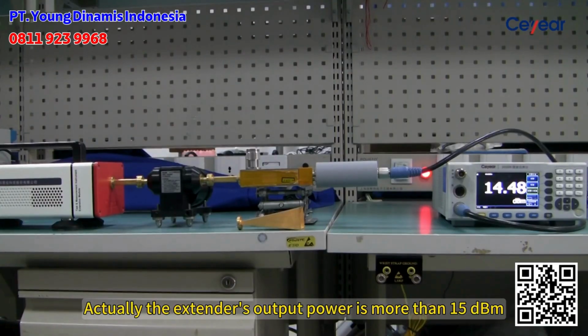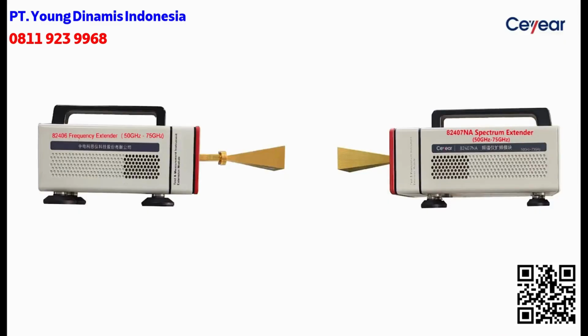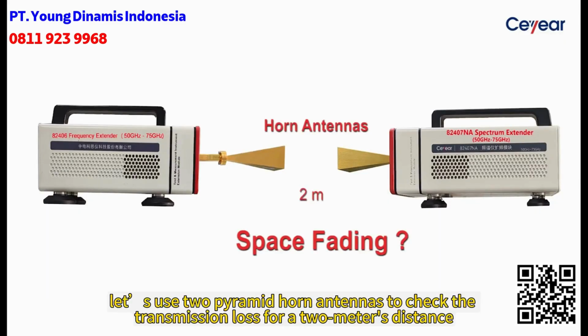Actually, the extender's output power is more than 15 dBm. But you can see there are two straight waveguides with about 1 dB attenuation in the path. Secondly, let's use two pyramid horn antennas to check the transmission loss for 2 meters distance.